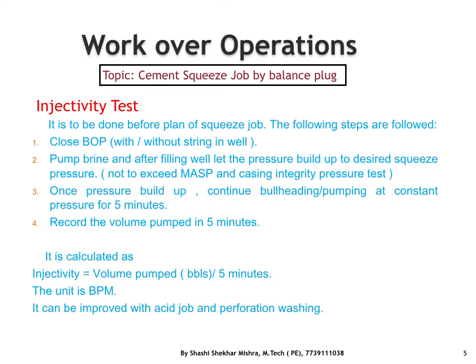So an injectivity test is done before the planned squeeze. Before that we close the BOP. If the string is there, then we have to close the annular or pipe ram, and if the string is not there, we have to close the blind or shear ram.